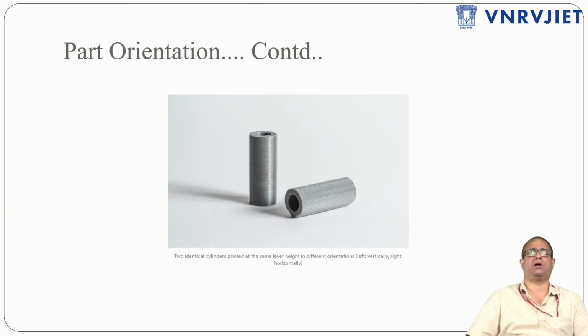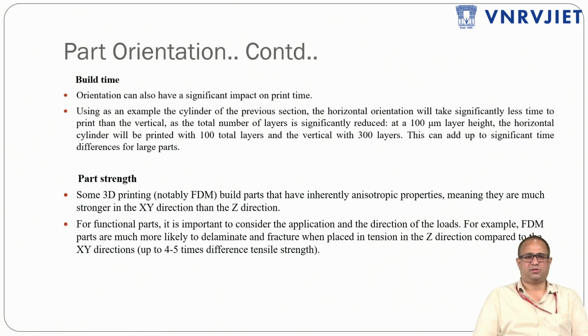Suppose it is a demo model or conceptual model which is just supposed to be shown, then orientation does not play an important role. We can lay it in a horizontal orientation also. But if you are looking from an accuracy point of view, always orient the parts vertically. As you can see, build time also depends upon the part orientation, because based upon the orientation, the layers are going to depend. These layers play an important role, especially to lay up the material, and time is also going to be fixed. And part strength.